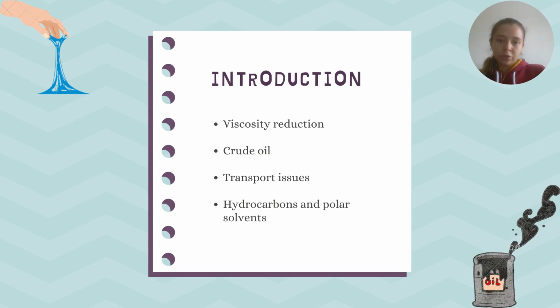This viscosity reduction is influenced by factors like dilution rate, oil, and diluting properties. Adding a polar solvent to asphaltene solutions decreases viscosity, and mixing hydrocarbons with polar solvents can enhance viscosity reduction. However, solvents with many hydrogen bonds are generally more viscous than hydrocarbons, so polar solvents with fewer hydrogen bonds are most effective in reducing diluted crude viscosity.